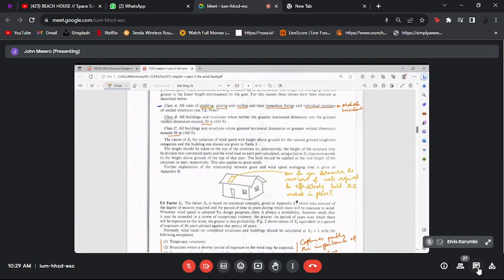And what happens is that if you have watched the videos of places where these winds have occurred, and nowadays we live in a very good age where everybody has got a video camera in their phone. So as it happens, you find somebody has shot a video and shared it maybe on some platform. You'll notice that as the wind comes into the area of the building, whether it is real life videos or even in movies, it is the cladding that first peels off, courtesy of the pressure that the wind exerts on the surface of the building.